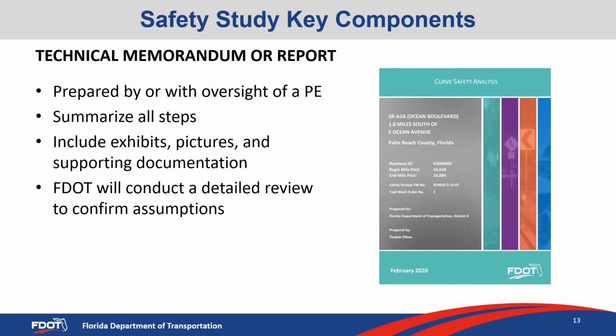All components of the safety analysis, safety study should be documented in a technical memorandum or a safety study report, depending on the magnitude of the improvements and how much documentation is required. This document should be prepared by or with the oversight of a professional engineer, summarize all the steps that we discussed before, as well as any additional steps that are taken or any other items that the engineer or agency submitter chooses to document. Include exhibits, pictures, and any supporting documentation that it is felt would help with the vetting, review, and prioritization of this project.